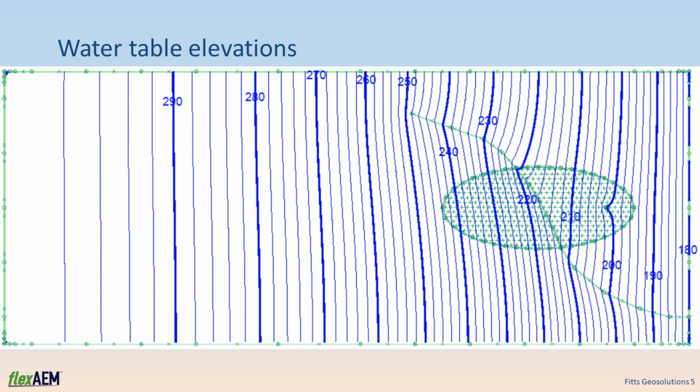In this demonstration, we will trace pathlines backward from the pumping well to outline the horizontal extent of the zone of contribution. We will also trace pathlines forward from a point location and from multiple points along a line to fill in the picture of the 3D zone of contribution. Finally, we will start pathlines over a large area of the water table up gradient from the well and trace them forward toward the well. By outlining the starting area of those pathlines that are captured by the well, we can find the area contributing recharge to the well.